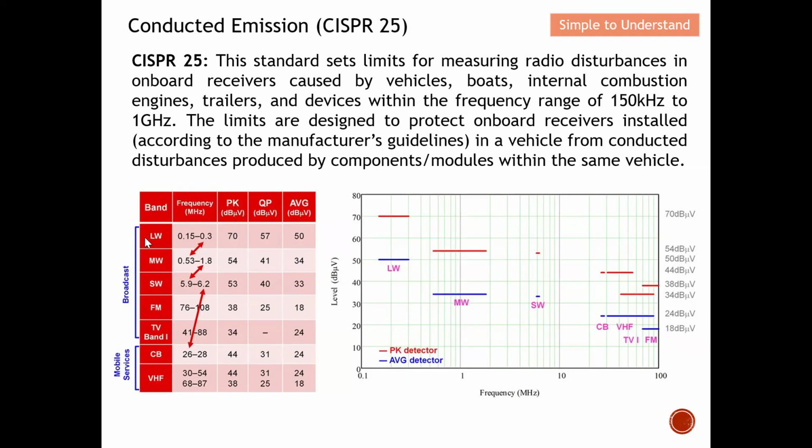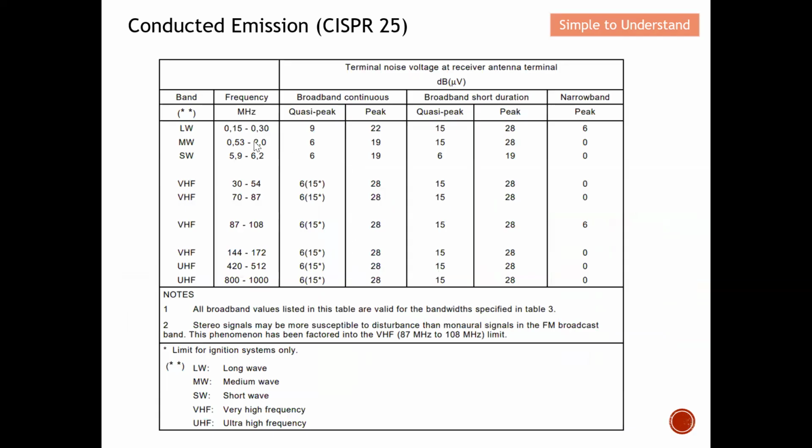Over here you can see that we will test in the long wave, medium wave, and also the short wave. The rest will not fall under conducted emission, mainly it will be radiated emission. But in short, we need to focus on the long wave, medium wave, and short wave. What are all these, I will explain on the next slides. This is the limit line, as you can see from here.